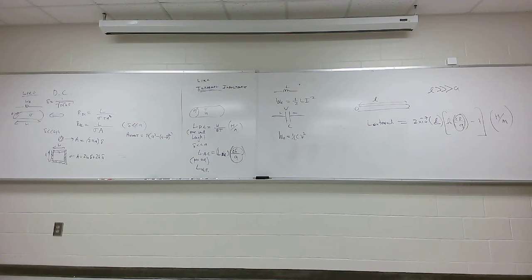They have a whole bunch of conductors that are woven in a way that minimizes the electromagnetic interference, the interference of one wire on another. And I can't get into that now. Just realize there are a lot of common ways that conductors are laid out, and they're easy. Those inductances, external and internal, are well known. I just wanted to put that up.